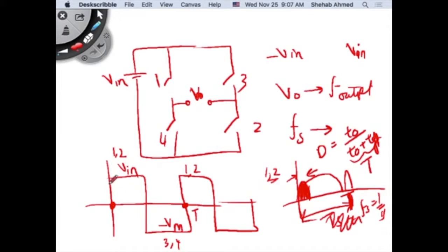So this is the frequency of the output. So if I'm supplying a 50 hertz or a 60 hertz system with this inverter, would it be a problem if I plug this computer into this outlet that is being supplied by an inverter that's feeding a waveform like this? Maybe. It depends on the input specs of this. If the input of this PC is nothing but a full bridge rectifier, no, it doesn't matter. If it's taking this AC voltage and just rectifying it, it does not really matter at all.